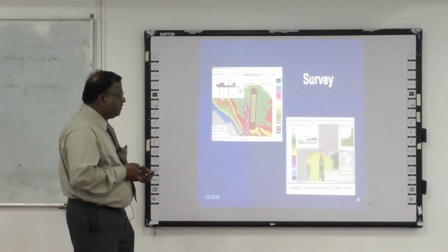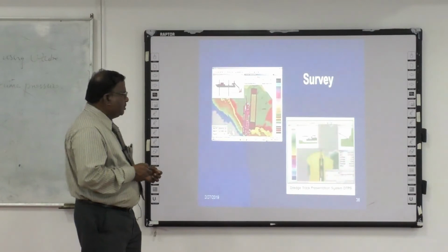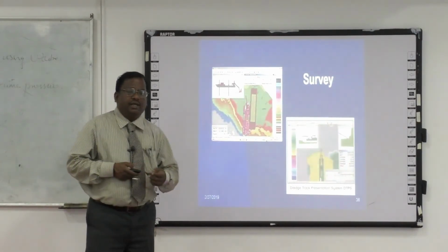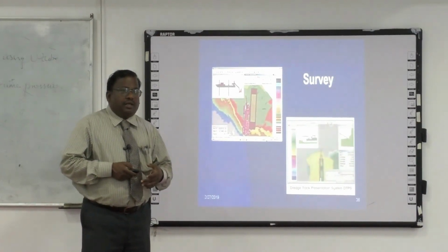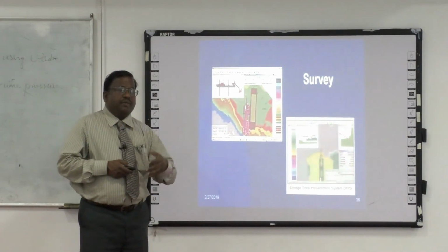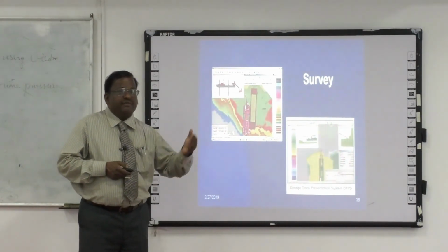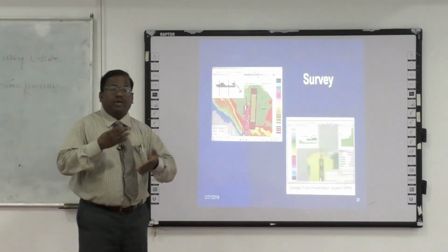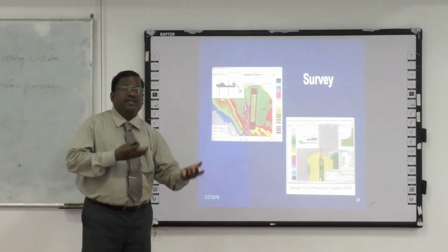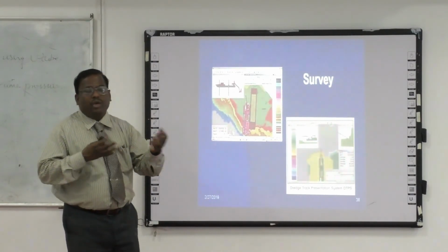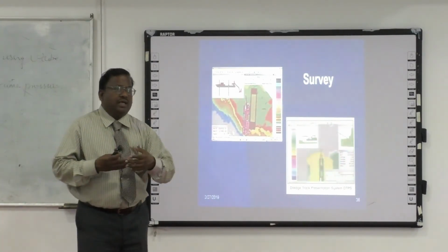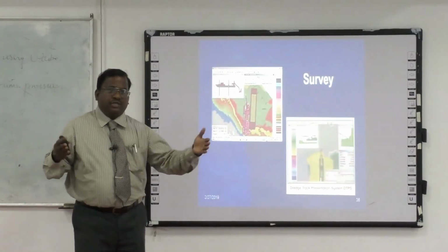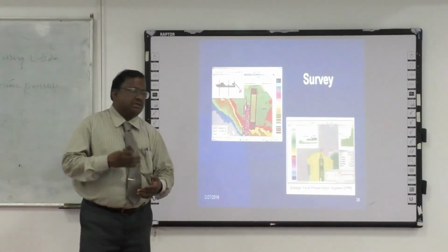And survey is one of the important ones. Before starting any dredging project, the foremost important point is that we have to make a survey of the region. Then we can determine the total area we have to survey, the total volume, and how much volume of dredging material will come. This will evaluate the time of dredging, project management as well as the cost of the dredging.